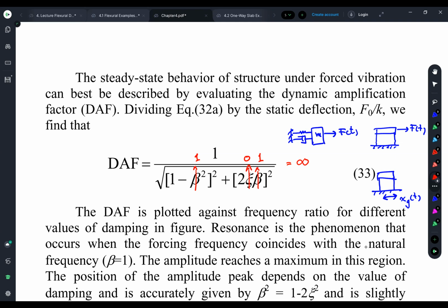If you don't have the damping, I agree with you. At resonance, you input more and more energy into the system. So the vibration of the building becomes larger and larger and goes to infinity maybe 10 hours later. The building collapses, we can expect something like that. If the damping is 0, theoretically speaking, the building movement will approach infinity, because you don't have any term to help your system or your building extract or remove the energy from them. Okay, hope you understand this.